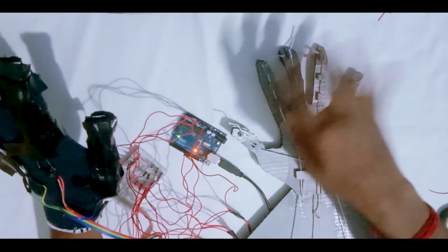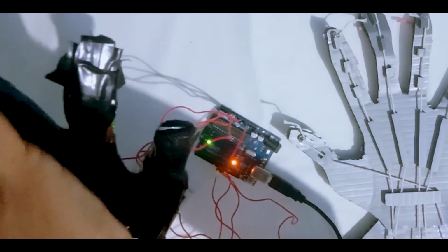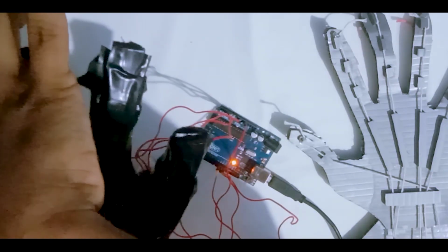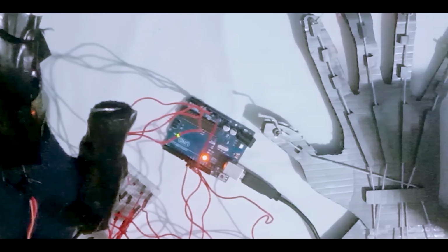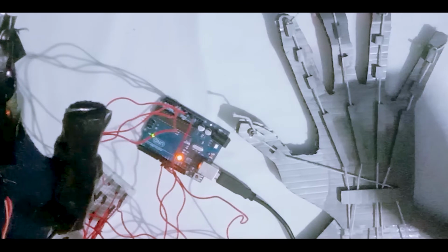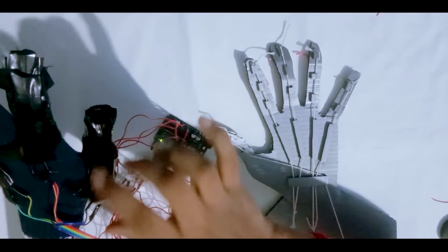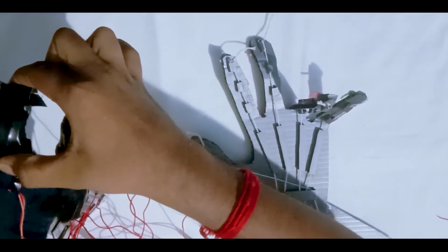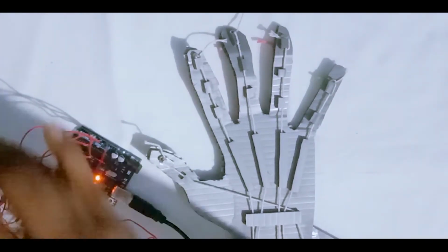So in this video we can see the working of animatronic hand. The flex sensor integrated to the gloves gives an input to the Arduino board on the basis of how you bend the hand, and the Arduino board assesses the signal from the sensor and executes the action based upon the preloaded program. Here the servo motors connected to the Arduino board using PWM pins give an output received from the Arduino board, so that the animatronic hand starts to bend according to how the servo motors rotate.